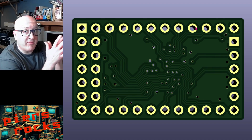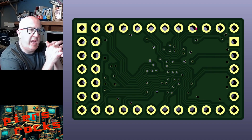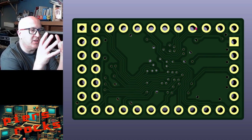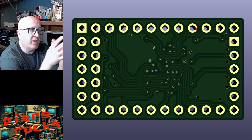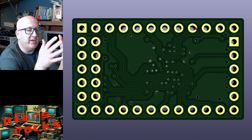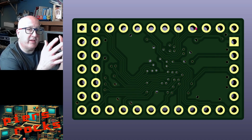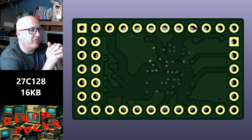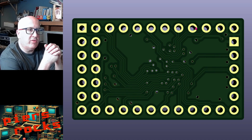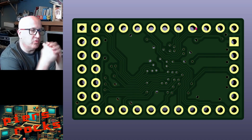I have actually squeezed on another couple of header pins in a subsequent revision of this, which I'll talk about in a future video. And I've also managed to use this same microcontroller with a slightly longer PCB to replace the 28C128 EEPROM. At least I've got a hardware design for that done. I've not tested it, I've not received it back from the fab yet, but I'm on the edge of what I can fit on this PCB, both component-wise and trace-wise, at least by putting all the components on one side, making them hand solderable, at least for me.